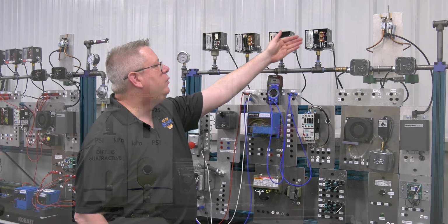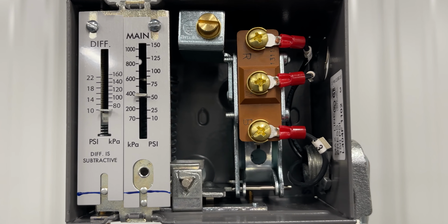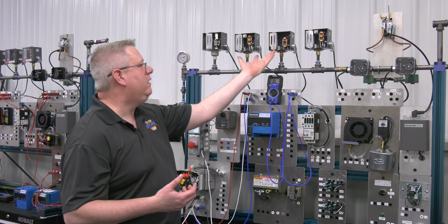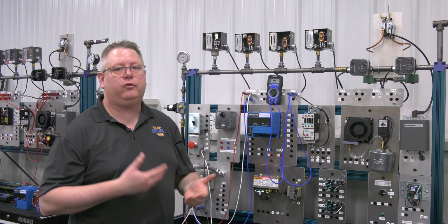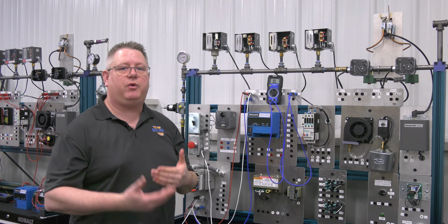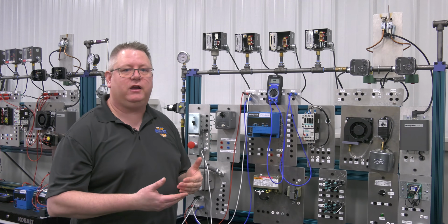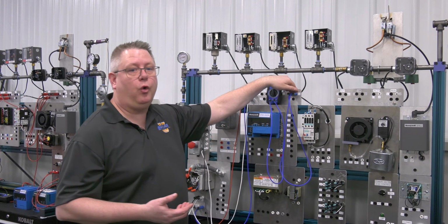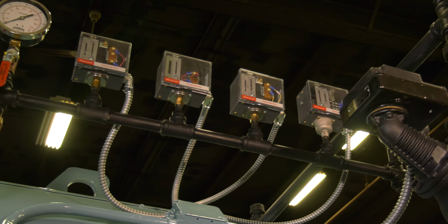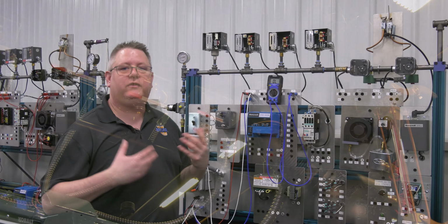Now, this switch, we are hoping to prove that we have pressure to allow us to run. And it's typically wired in a way that is a little different than our operating and high limit. These are making and breaking the burner control circuits. Instead, our low fire hold device is actually making or breaking our firing rate circuit or interfering with the automatic firing rate control. So we will wire this on the normally open contact, because when the boiler pressure rises, we want that switch to close and to allow the firing rate control to do its typical job.